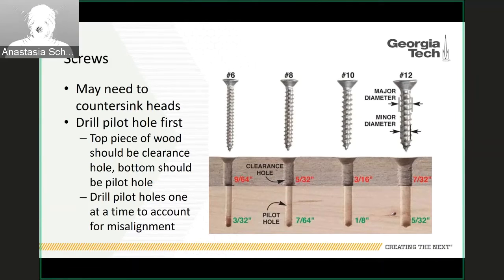If you were drilling in, say, 4 screws in a row next to each other like this, you wouldn't want to drill 4 pilot holes and then put 4 screws in. You're going to want to drill your pilot hole, put your screw in, and then do the next one, and so on. This is so if you end up with any misalignment, which you probably will, by the time you get to the 4th screw, it'll still be able to fit in.